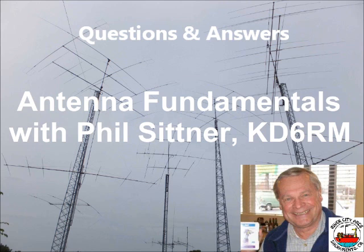But there's other ways to do it. There are what typically are called L matching networks, which is a combination of a capacitor and an inductor that you can do at the antenna. You can change the characteristics of the antenna. Remember I was talking about the ground plane and how you can bend those radiators, the reflector elements of the ground plane, and that'll get you closer to match.